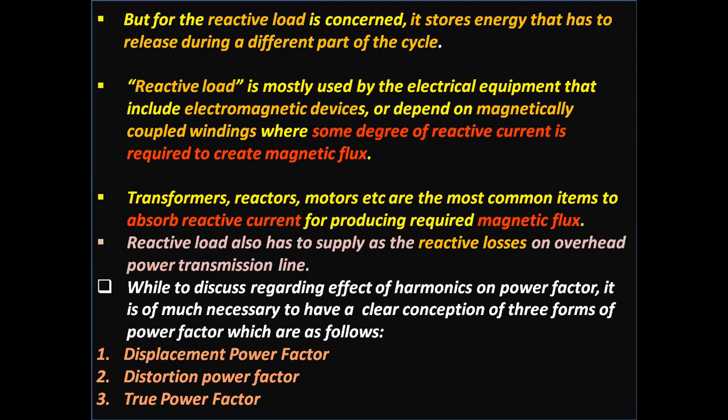But as far as the reactive load is concerned, it stores energy that is released during a different part of the cycle. Reactive load is mostly used by electrical equipment that includes electromagnetic devices or depends on magnetically coupled windings, where some degree of reactive current is required to create magnetic flux.